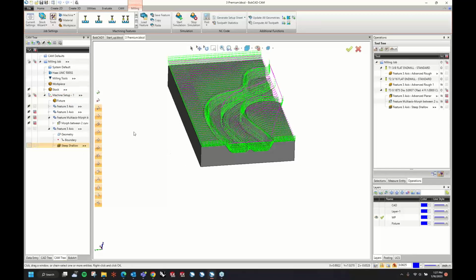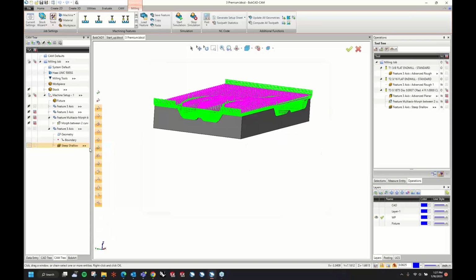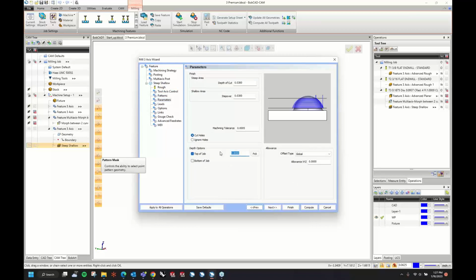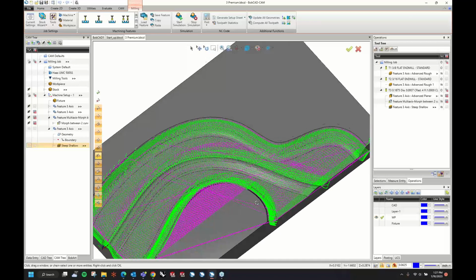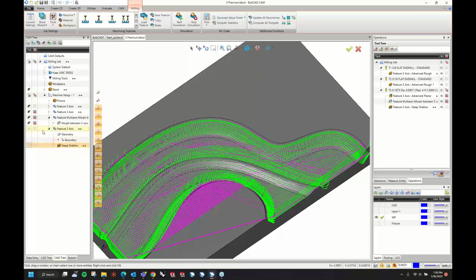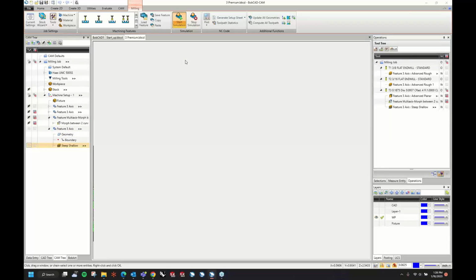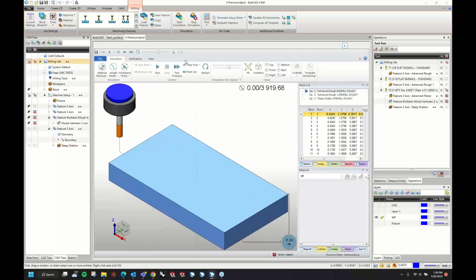But I'm still going to run into the same thing with the working on the top of the model. It's retracting all over the place. So let's actually drop that down a little bit. Top of job. Compute. So you can do it with this steep shallow if you want just something really quick. And I'll show you what it would do before we move on to the next model we were going to take a look at. And we could always come back to this one if we have time to do the multi-axis across the whole thing.